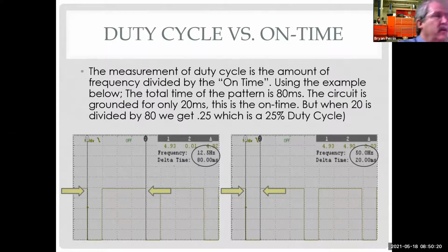We got some captures that are coming up, and as we get into other systems where you'll see this, we're doing engines next. I've got stuff in variable valve timing where you'll see the duty cycle concept. So at this point, I'm really more about the concept of it, so you know what duty cycle is. By the end of the class, you're going to have seen a lot of pictures, because I use it to describe different systems, whether we're looking at EGR or variable valve timing, anything we're using that duty cycle control with. I have a lot of scope patterns that I pull up to show, here's where the computer's turning on, here's what we're doing, here's how it affects other things, so we can see the relationships.